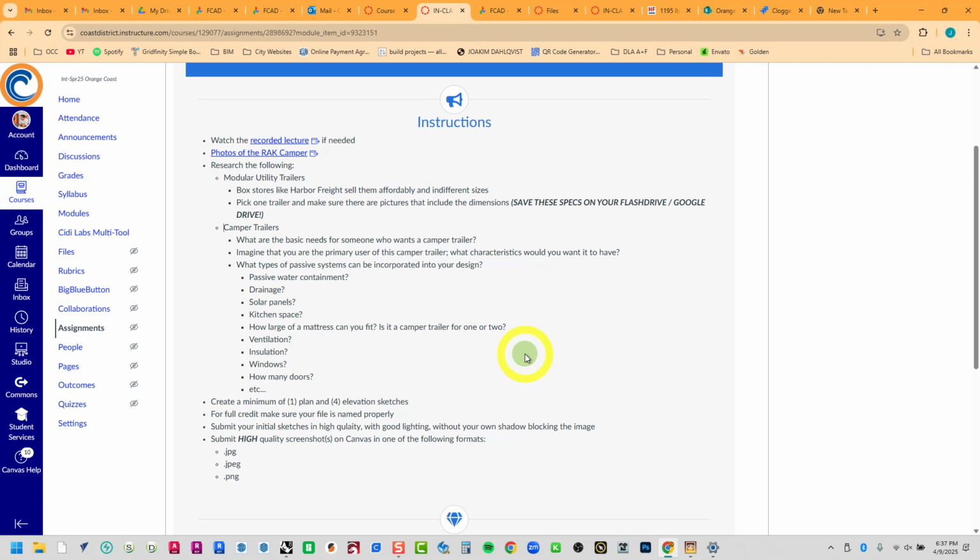Insulation. Is there a way we can insulate these panels? Look up different types of insulation. There's rigid foam insulation. There's denim. There's rigid board insulation like OXIS. Look up OXIS. That's a great rigid foam and sheathing type of insulative panels. They're basically construction plywood with a small layer of foam, so it actually gives you some shear properties, keeping your camper trailer really nice and straight and rigid, as a rigid box, but also it has insulative properties, keeping the hot out, keeping the cool in, vice versa. Would your camper trailer have windows? Would it have any doors, etc.?